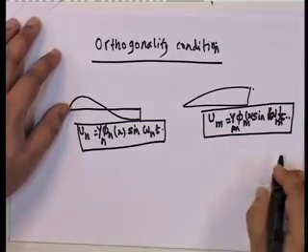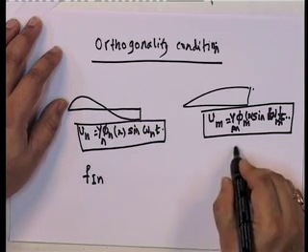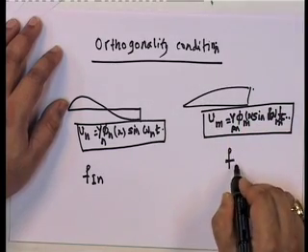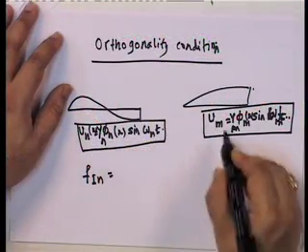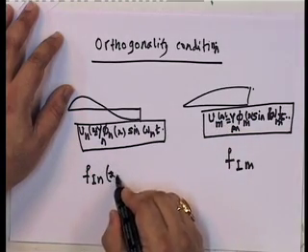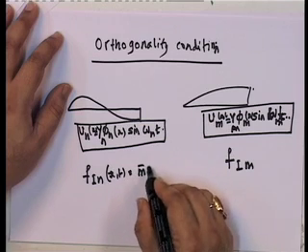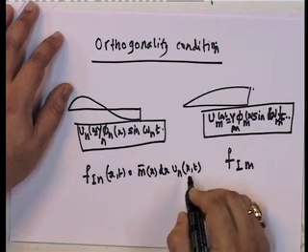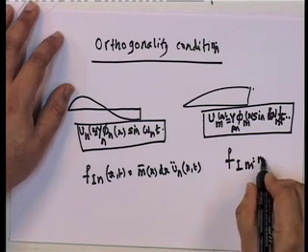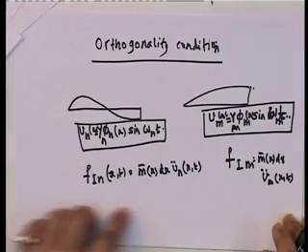So if we look at this, if we get an inertial force due to this load, we'll call it Fin, an inertial force due to this displacement, I'll call it as phi im. What would phi im be equal to? If you look at it, this is Vn x of t, this is Vm x of t, this is also phi in x of t, at a particular point. This is going to be equal to m bar x dx, that's the mass, into Vn x of t double dot, and similarly this would be equal to m bar x dx into Vm x of t, because this is the acceleration.